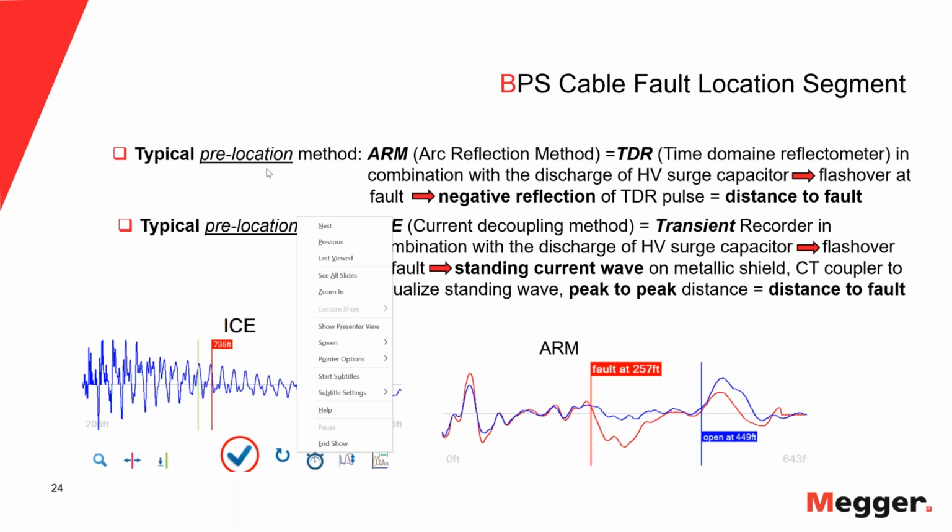That's very important to understand. If I have a non-flashing fault, they don't work, and I need a different method, okay? But for flashing faults, and in these types of cables, solid dielectric cables, for the most part, we have flashing faults. These are the two typical methods being used today.